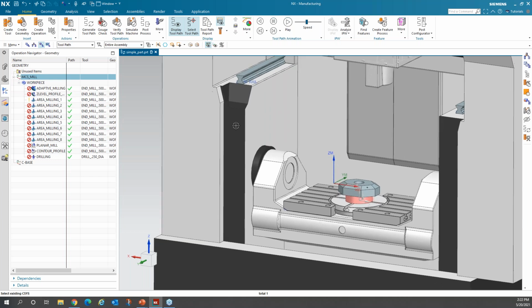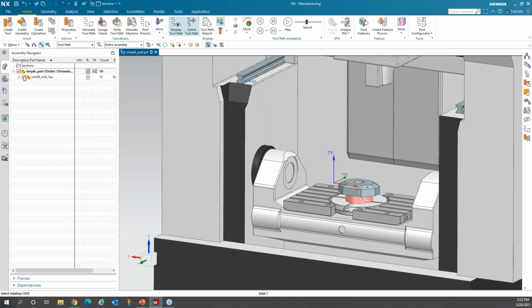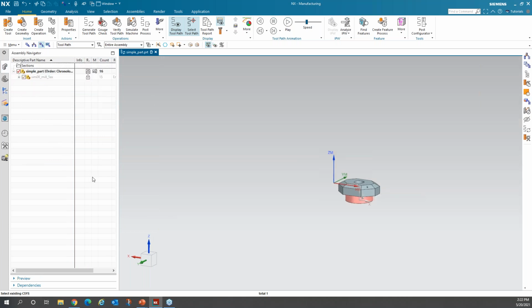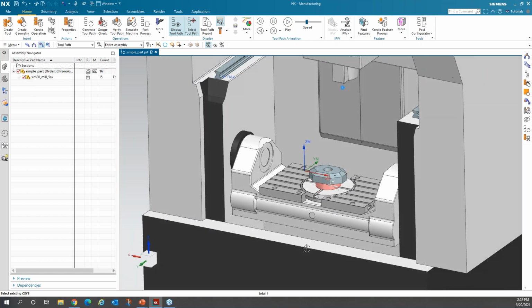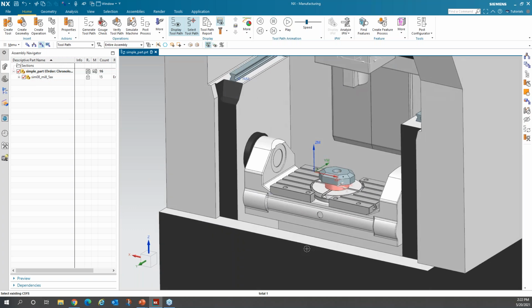All right, the next question we have is, will preferred rotary solution work on all postprocessors? That's a no also. It works on this postprocessor, but because that's for this machine, and they just made that preferred rotary for the new machines.